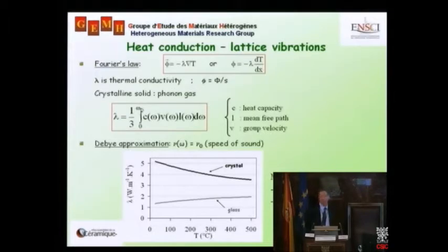You can then apply kinetic theory of a gas to obtain an expression which involves the heat capacity at a given frequency, the group velocity for vibrational propagation, and a very important factor, which is the mean free path. These are the three factors which control thermal conductivity, and often we will make a simple approximation where we assume that the vibrational propagation speed is basically a constant, in other words, the speed of sound, the low frequency limit.